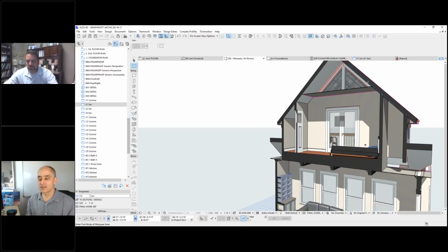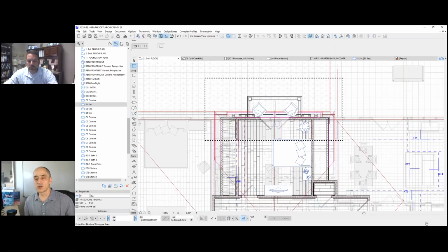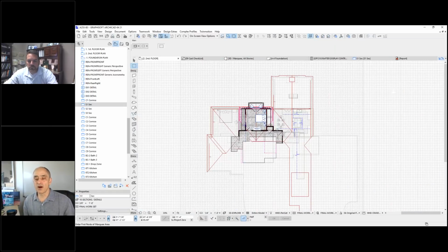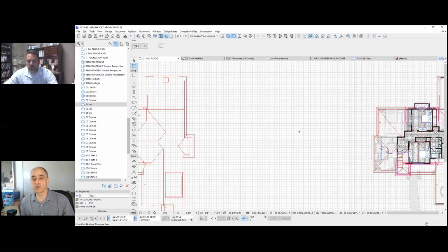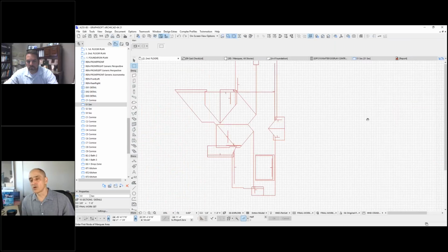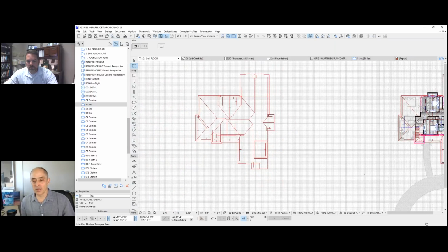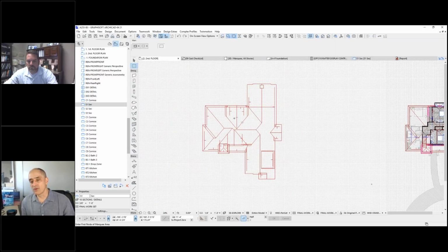So the fact that Chip is putting the line based on those interior walls, even if those interior walls aren't the structural support, or not what you'd call the plate height, it's just a convenience for how you define, in this case, the ceiling height that he wanted to achieve. So it's not structurally any different than what you might think. It's just from a control standpoint, this is where he's setting the height.